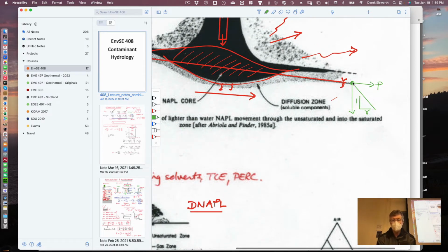But what this allows us to do is, if we want to, we can extend this back up to the surface. And that says that in this zone here, the vadose zone, the tension saturated zone, it's saturated by tension. This is a negative pressure that it has in here, and it's because of this capillary rise within the system. So that's physically what's going on.